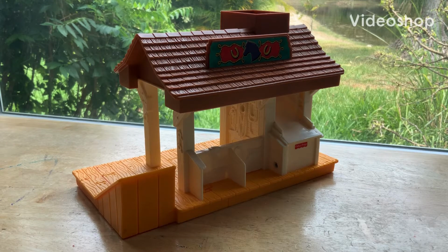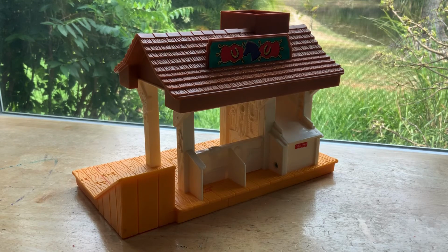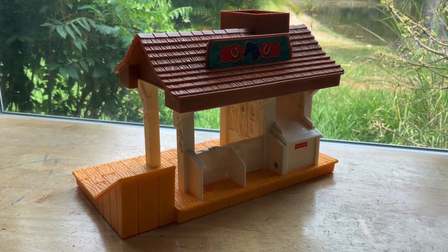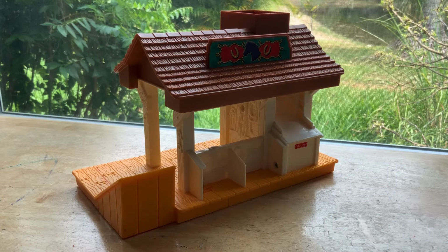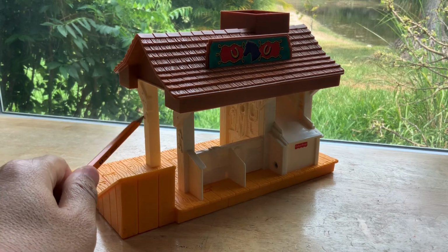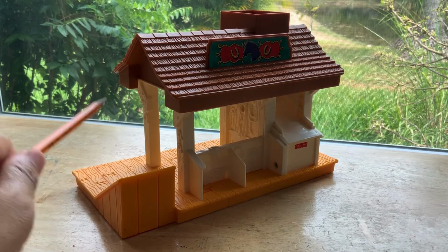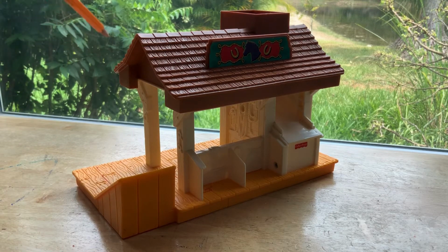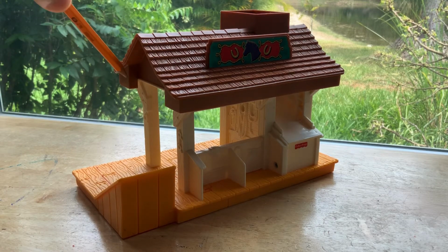The topic today is buckling, and for buckling, we want to see how the structure behaves under a compressive axial load. What are the structures that have a compressive axial load? For example, we're talking about the column in the house. The column carries the load from the roof, the weight of the roof goes down vertically to the column, and that creates a compressive stress on that member.